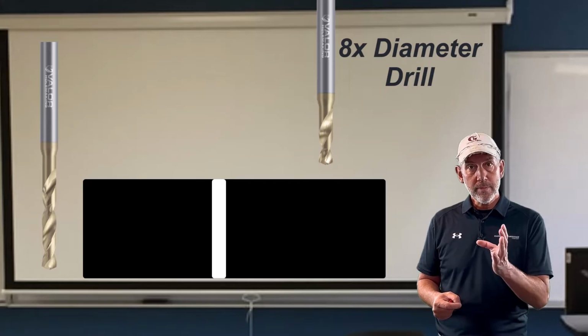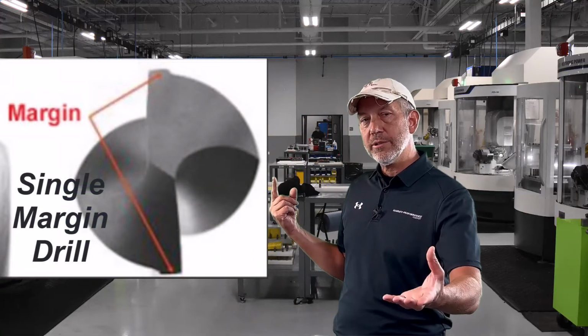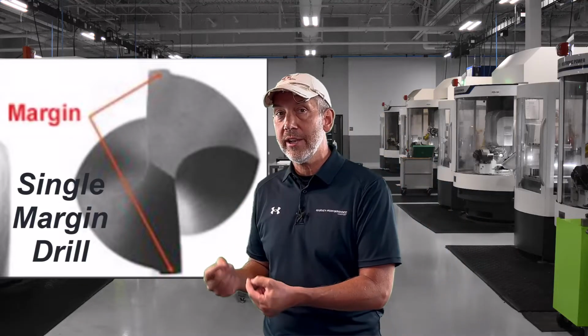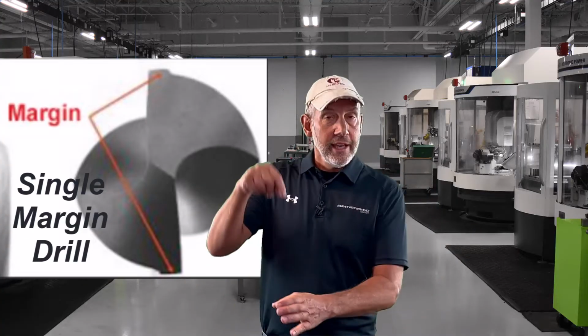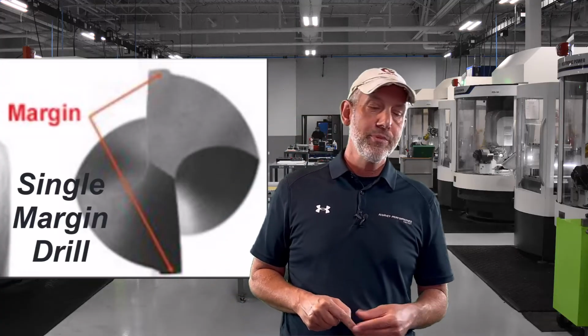Okay? Now, this is where some of the fun stuff starts. Everybody has a tendency to make drills with different margins on them. Margin is the cylindrical round on the outside of the tool. That's a margin. It doesn't cut. It's cylindrically ground. It has zero relief in that margin. What it does is it stabilizes the drill in the hole. When it's cutting, it stabilizes the drill in the hole.